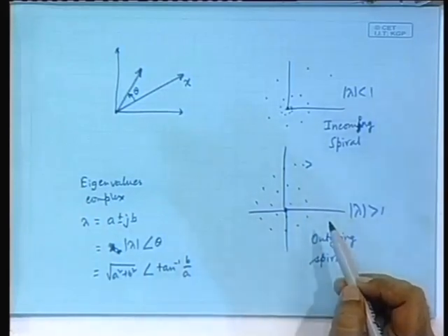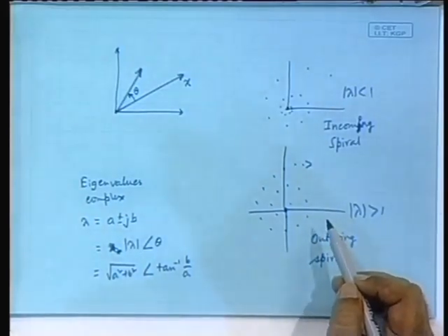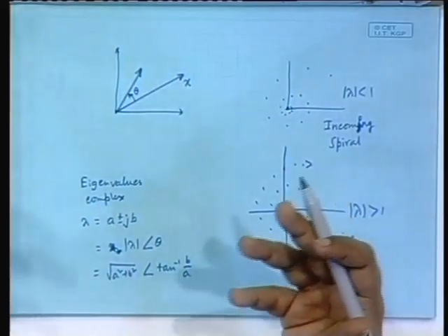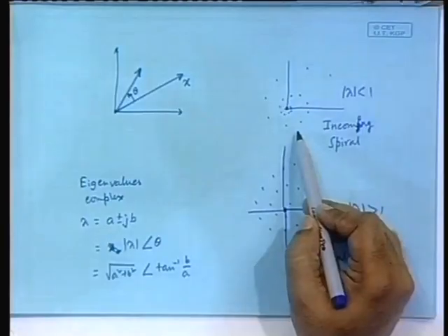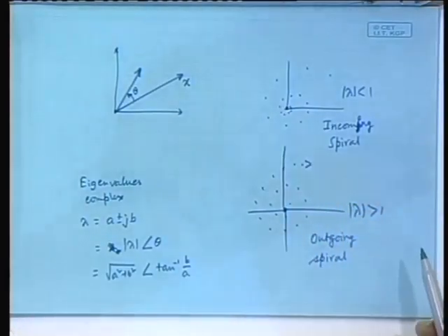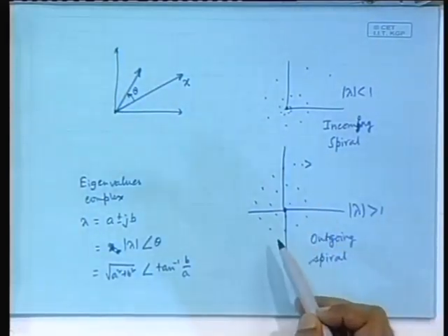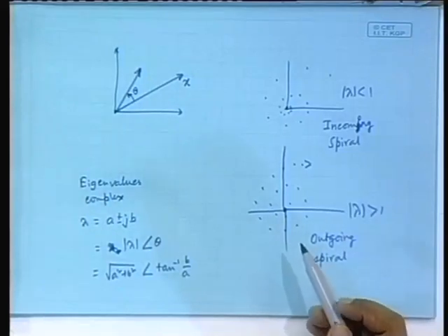This specific term is used where the eigenvalues are complex conjugate. It could either be a stable focus or an unstable focus. If one says it is a stable focus, you know that the behavior around is the incoming spiral, and if one says that we have an unstable focus, you would understand immediately that one is talking about an outgoing spiral. Okay.